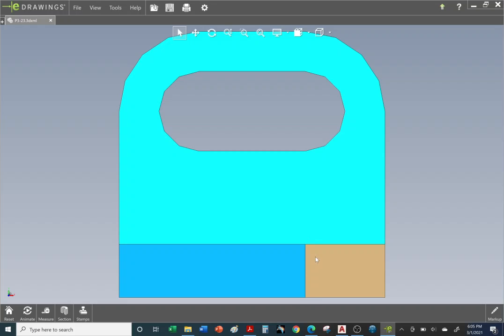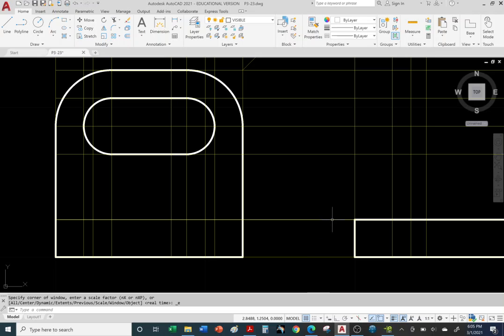All right, so let's take care of that visible object line, and then we'll do the vertical one. Let's go to the visible layer, line command, and we're going to go off of this vertex, right? Everything lines up. I'm going to turn on ortho. It guarantees a horizontal or vertical line unless it tries to snap to something. So you want to have object snap turned on. If it's blue, it's active.